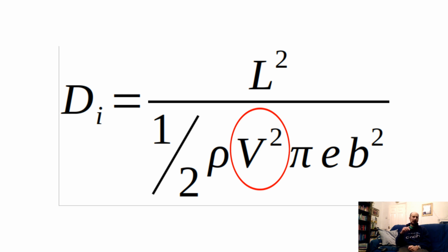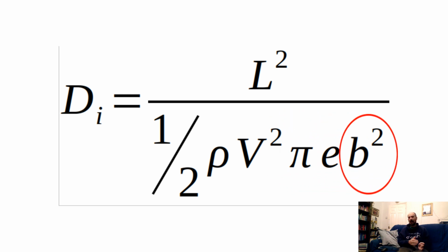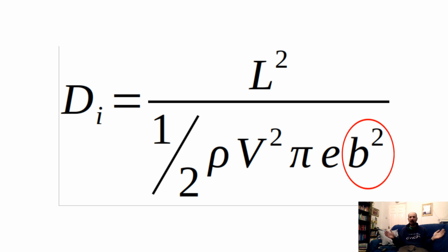of view. If we start to get into the design parameters though, we can see that a bigger wing span reduces the induced drag, and if we're increasing the span, we'll probably want to reduce the chord to keep the area constant, which then leads to the higher aspect ratio. So this is where a higher aspect ratio glider tends to have more performance than a lower aspect ratio glider, because it means it has more wingspan for the same amount of area. Now that is useful from a design point of view. It's one of the basic facts that we know about glider design.